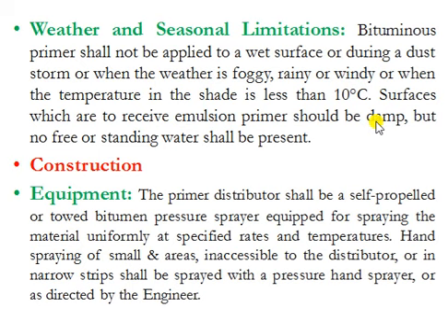So there are some criteria for spraying of a primer. The spraying of primer depends upon weather, and there are some limitations for that. The primer should not be applied on wet surfaces. The primer should not be applied during a dust storm, and during fog we should not apply the primer. During the rainy season or during rain, the primer should not be sprayed.